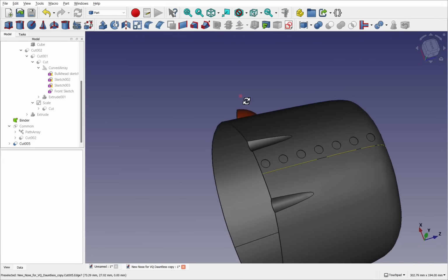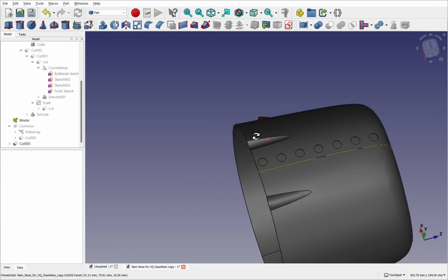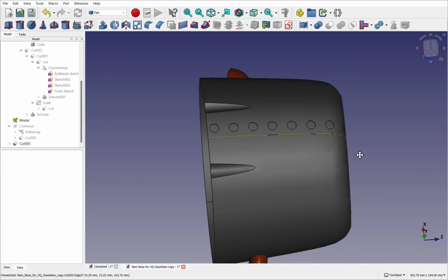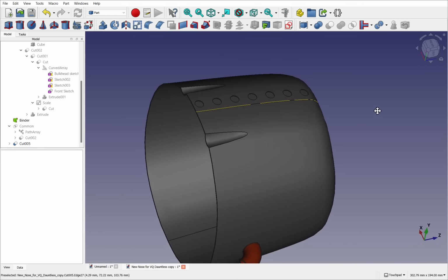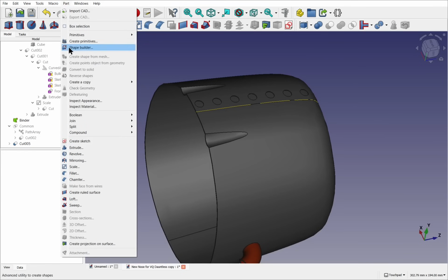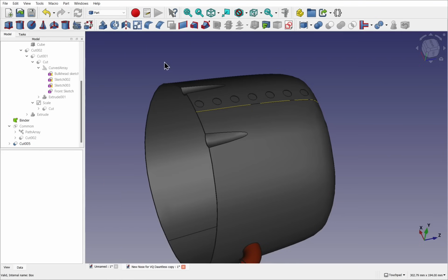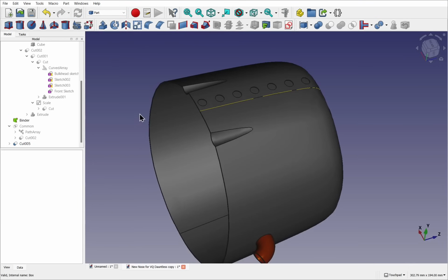With this object, I would cut this in two because we've got symmetry going across here, do the rivets across one side, and then create a mirror going across the other. That's quite easy to do because we create a plane and use the split, the Part, split, and then slice apart. So plane through the center and slice these apart, create the rivets, and then mirror this across. So that's for the rivets.